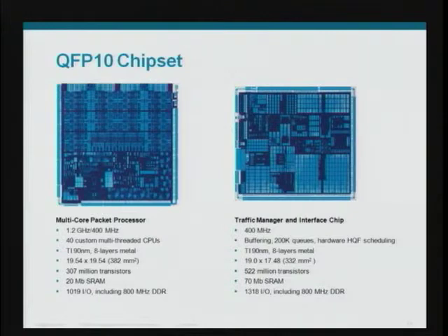These are the two chips in the chipset. The left chip is the packet processor. The 40 processor cores, that's one right there, about 4,000 microns wide and about 590 microns tall. It's a nice regular looking object. This area is an array of 8 crossbars that connect groups of processors to the resources. There's a large second level instruction cache at the top, with 512 kilobyte capacity.